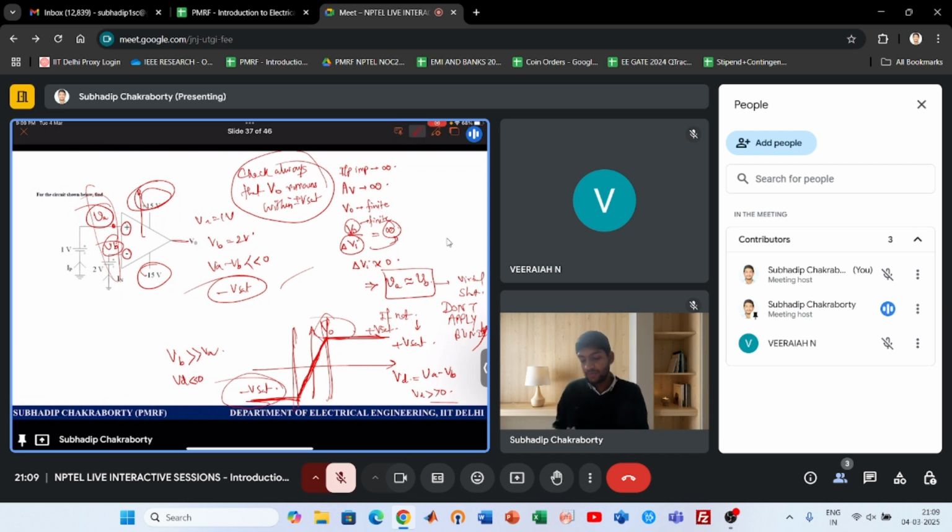If it is crossing, that means your input side is not in the amplification region. Your input is either driving the op-amp to plus or minus Vsat. That is based on the output characteristics of the op-amp and the input differential voltage applied. That is the rule of how the op-amp functions and how it is designed.